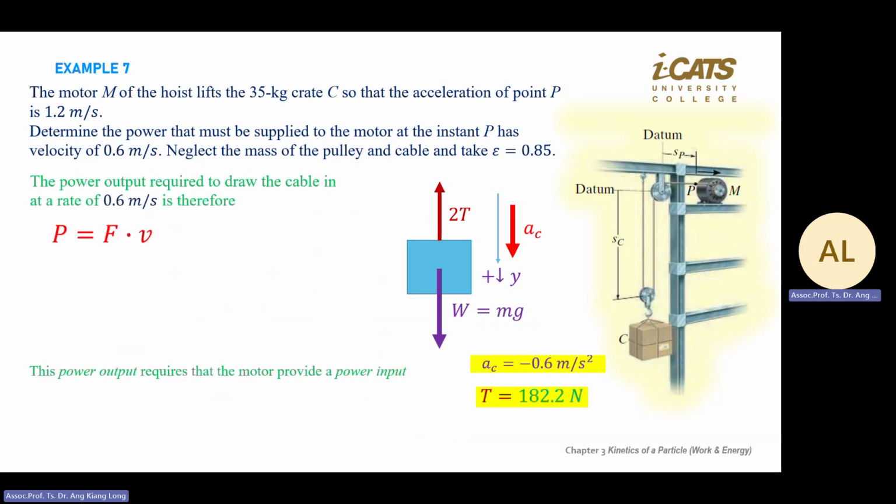Okay, so you know power equal to force multiply velocity, or power equal to work divided by time, or time differential of your work. So in this case, the question does not ask you to find work, so don't go and do the work procedure. The question asks for power, so you do the power question, then find anything that is in the question. In this case, velocity is given, so the hint is you need to use P equal to FV.